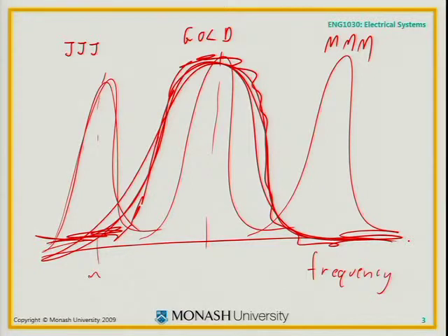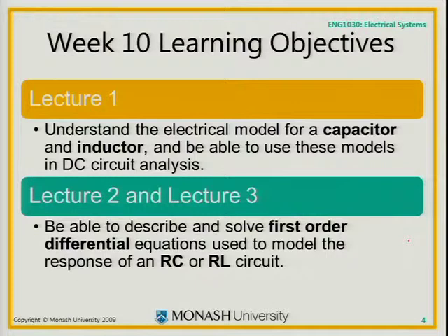We need capacitors and inductors, and as soon as we've got those elements, we can make something behave this way, that at lower frequencies than we want, we can get rid of the signal, we can reduce the voltage if you like, and at higher frequencies than we want, we can make the voltage gain drop off. But in the middle, bang, we've tuned it to that particular frequency. How do we use inductors and capacitors to do that? Fundamental part of any radio receiver is this tuner, and inductors and capacitors play a critical role.